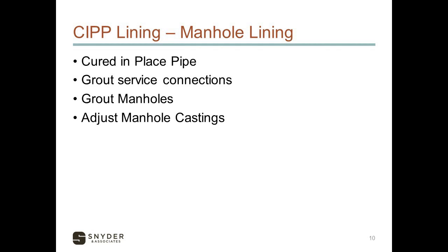The sewer companies have these small robotic crawlers that can go through your pipes. They can televise them. They can see issues that we cannot see from above the ground. And they can also pump in and pressurize some chemical grout into that soil, which basically turns it into cement.